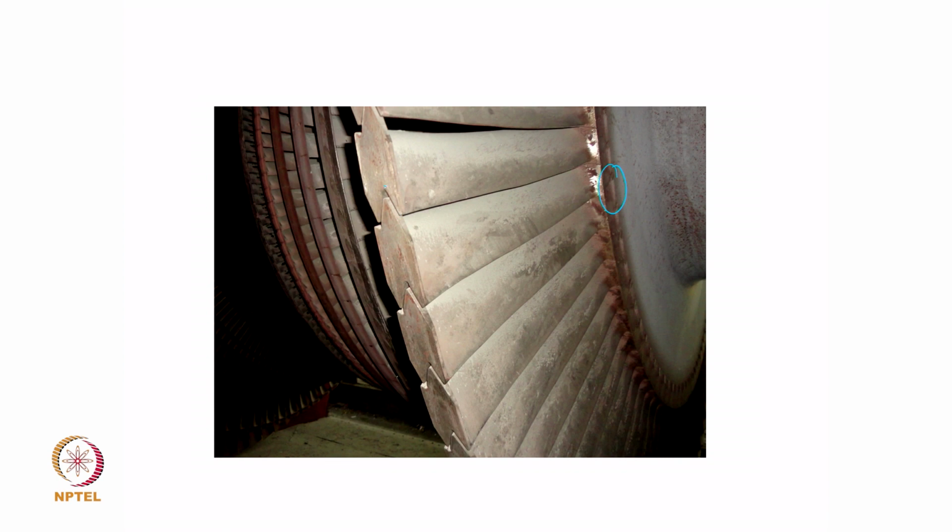these kind of shrouds. Okay. So, the tip of the blade has these kind of Z shape projections, and so on the trailing side you will have this kind of a slot, and the previous blade's leading side will have this kind of a projection. Okay.